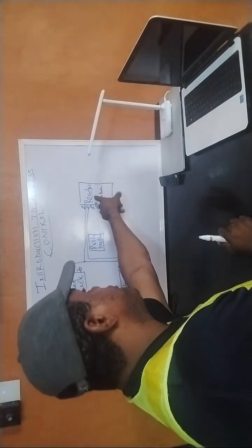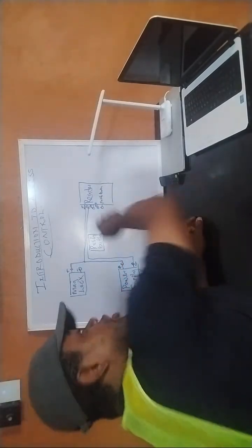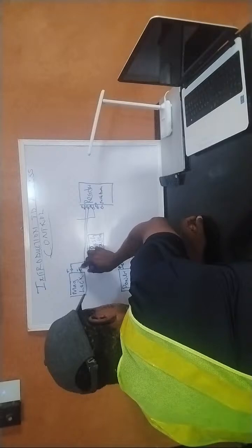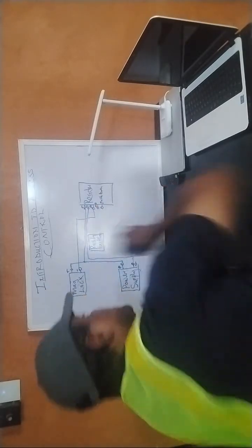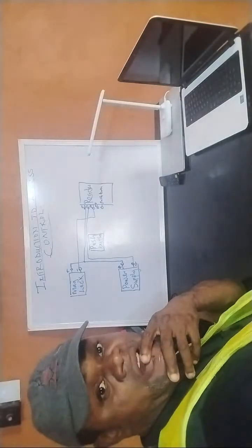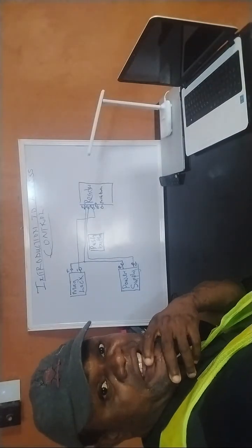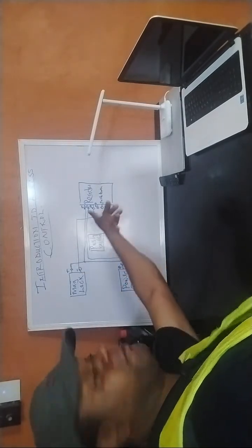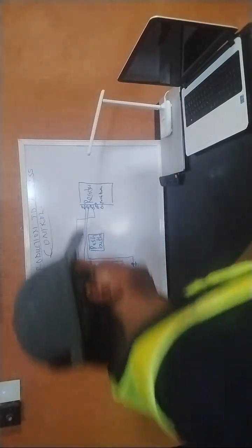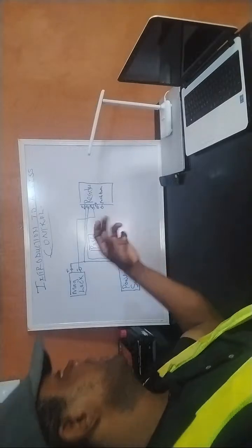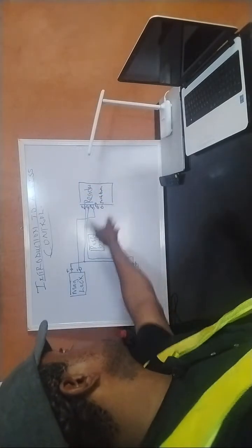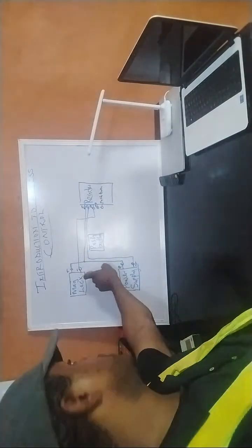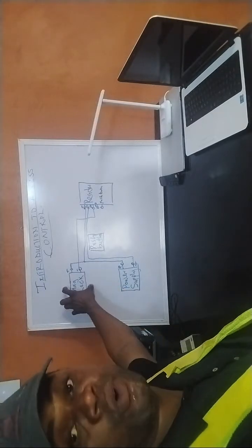So it is right for me to use the normally closed of this. So I take the normally closed of this. Watch this. It goes all the way, and I take it to this contact. Is that clear? I take it to that contact. So already I'm having power from this to this, the normally closed. So one thing you should understand is, make sure your terminal here is to enable this, because this is bringing a negative signal, or I say ground signal, to this to make this one active.